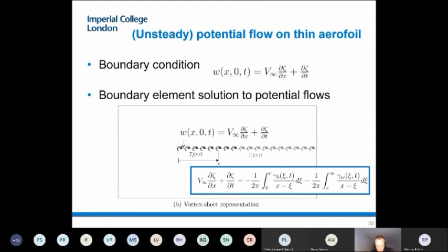So once we have that, then what we do is to superimpose that gamma divided by 2 pi r, and when you look at the signs of the forces, when the x is positive, that's a negative velocity. So the velocity that the flow is seeing, that's what we defined before on the airfoil, is equal to the velocity induced by that distribution of singularities. And that becomes a very simple equation to solve. It's an integral equation in which we need to solve for gamma.